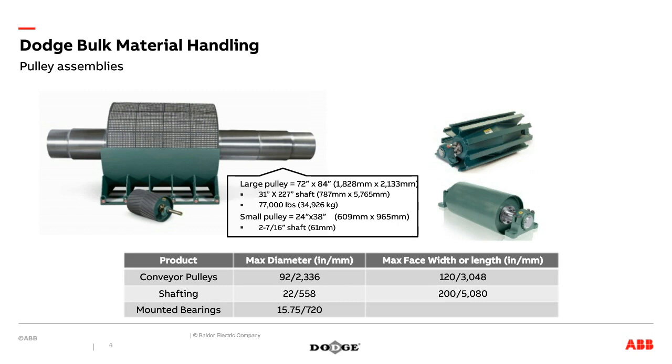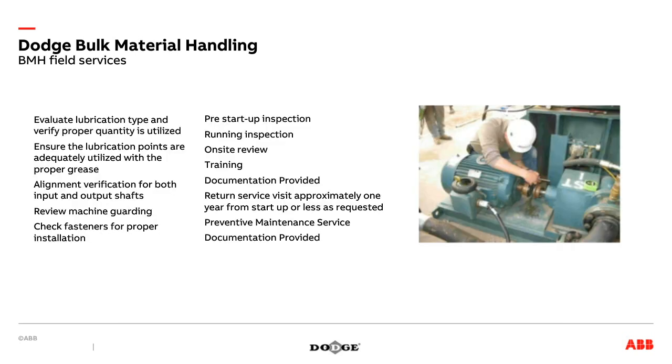The final piece that we're going to discuss today would also be field services. Required field services, in addition to designing the application and having the right product portfolio, obviously being able to manufacture and assemble all the products, but once they get on site, being able to commission them by having people actually come out and check lubrication, check alignment, check fasteners for proper installation, checking guarding, and training the maintenance staff, making sure they know the products and have all the installation manuals.